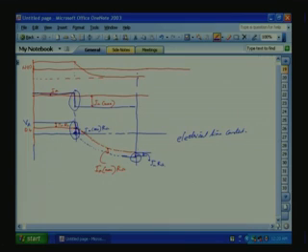Okay. So, the electromechanical time constants we will come to later. What we want here is this smooth transition, which is possible because we are controlling this armature voltage such that always maximum negative current is taken from the machine as the speed varies. And once it comes to the required speed, quickly we come to the required driving current for the driving torque.